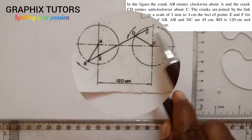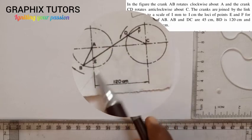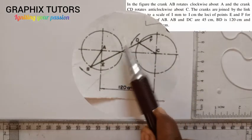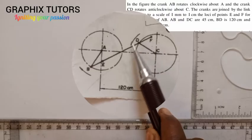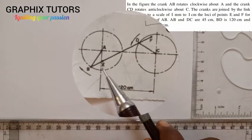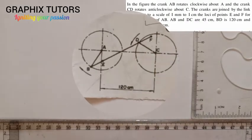So this is the link that is joining both of them. We're told that this crank AB revolves in a clockwise manner like this, while the crank CD revolves in an anti-clockwise manner, and it is denoted using this symbol here, the arrow going backward. Now, we are told to draw the loci of point E and point F.